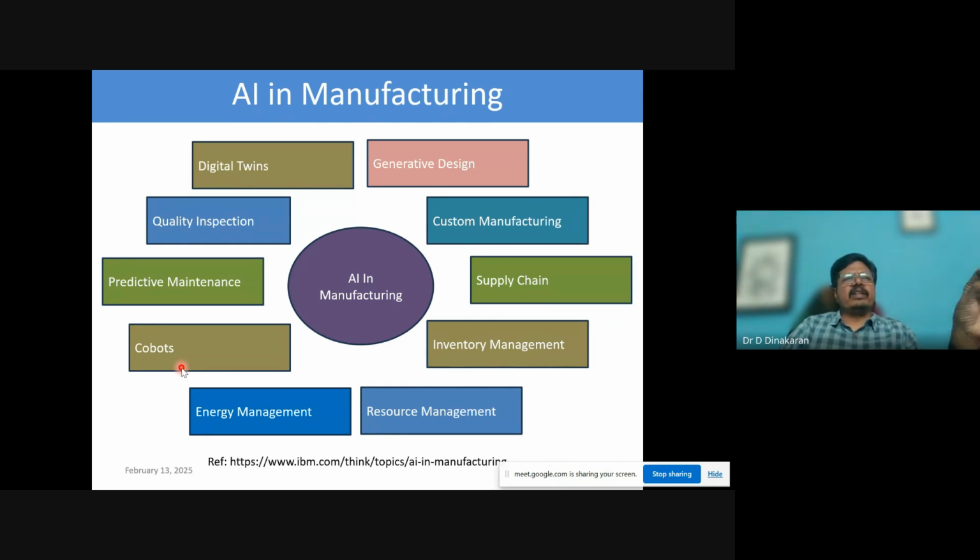When the sequences are very, very complex, when the sequences are not connected in terms of technology or in terms of size or dimensions of the component. Say the robot has to handle a small screw and it has to handle a 5 kg weight. For both things we cannot use the same kind of gripper design, right? So we can ask the robot to handle the 5 kg weight, and for the lighter thing, requiring less effort, the human being will take that screw and put it there. Like this, robot and human share the platform in doing that work.